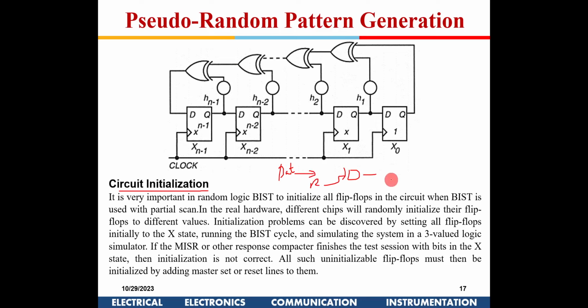So what you get here is garbage; you can't make sense out of it. At the receiving end, you have another XOR gate and the same pattern generator there, and the two pattern generations will be in sync. Again, you do one more XOR and you retrieve your data. So the initialization of this data, although the hardware will be the same for every mobile user, the pattern will differ: when I am speaking to Jay, the data fed here for generation of encryption will be different.